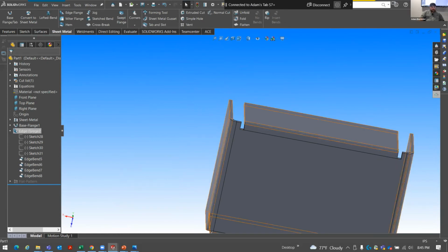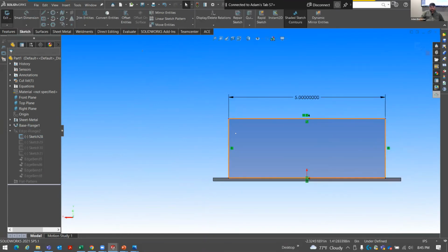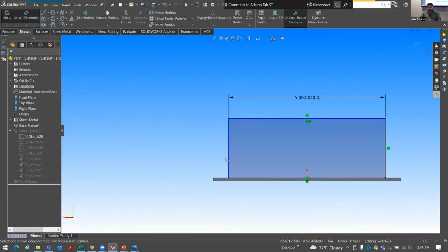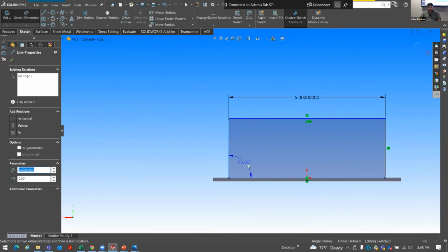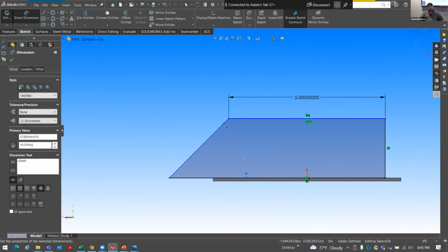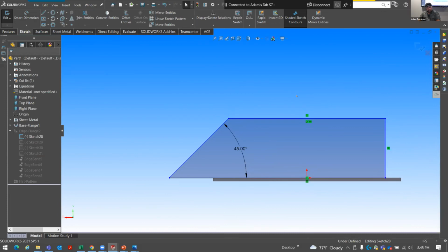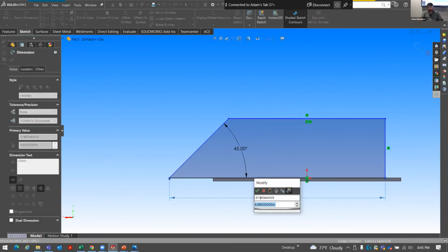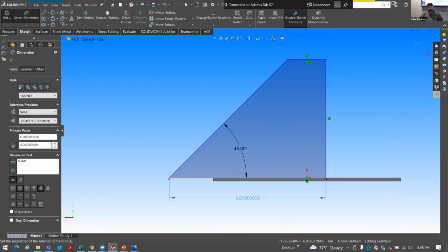Along with that, and I'll go back and show you another real quick way of doing it too. And you can again pick any one of these sketches that you want to edit. You could go in and even modify this one step further. That when it first created, it also gave some relationships to it, that these lines were vertical, this line was horizontal. But what if I really didn't want that line to be vertical? I wanted to add a dimension to it and say that that really needed to be chamfered at a 45. But now look, the dimension's up here, so maybe I didn't need that dimension up here. Maybe I needed it down here. Just moving it all around in it. But that's because I have it set to this midpoint.